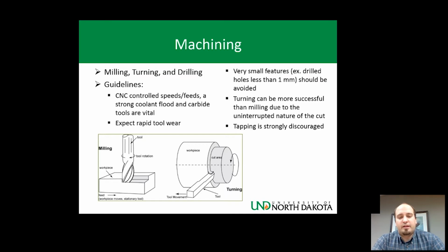When milling, turning, and drilling is done on SMAs after shape setting, particular care needs to be given on how much heat is being generated. When doing these operations on a material like nitinol, it can be difficult. Nitinol is a hard material in its cold work state. It is also extremely abrasive due to its tough titanium oxide layer on its surface.